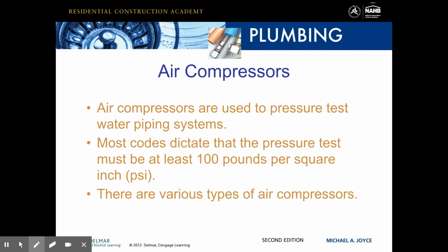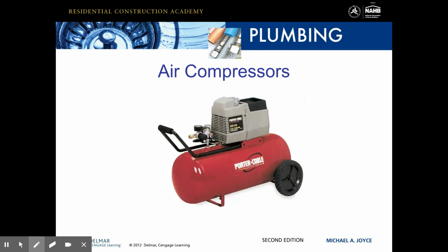Air compressors are used to pressure test water piping systems. Most codes dictate that the pressure test must be at least 100 pounds per square inch. And there's various types of air compressors. And here's a portable one.